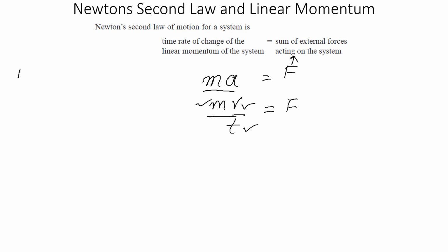If you remember, the extensive property with capital B, you saw this term in our Reynolds transport theorem. So now here B is equal to mv. Our extensive property is now the momentum of our system, and by system I mean fluid. In the previous conservation of mass section, our extensive property was mass only, and now we have studied that portion. Now we are going to study this portion in which our extensive property of our system will be momentum.